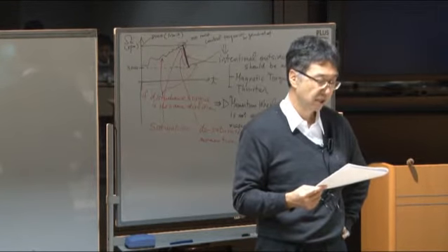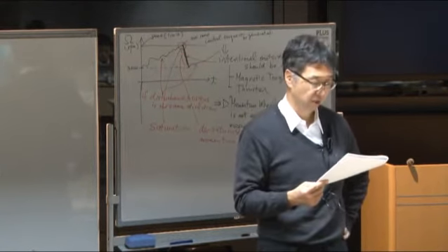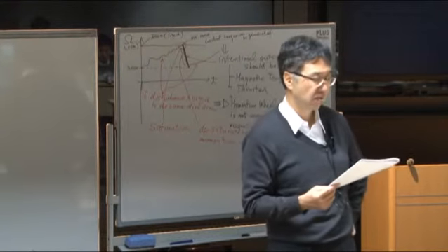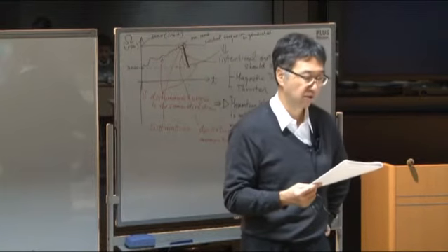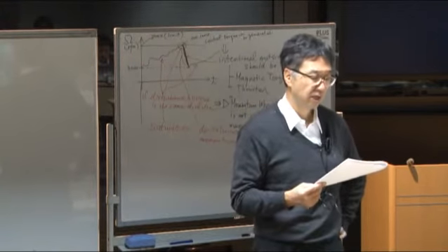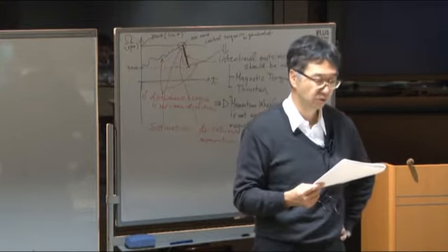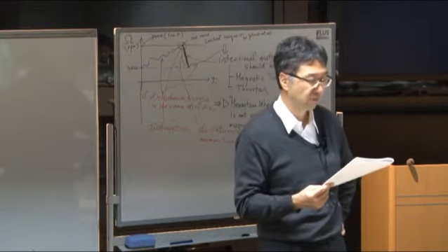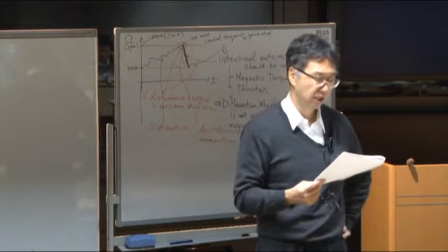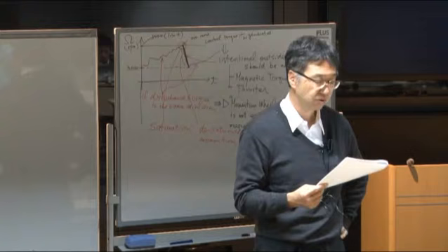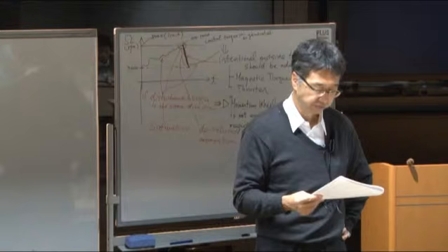Okay, so dual spin satellite has two meanings. One meaning is that this kind of long cylinder is possible without violating the stability requirement. So this is very good for installing in the rocket fairing. Another merit of this kind of dual spin is that you have the platform which does not rotate very fast, so you can implement an antenna or camera on the platform because it does not rotate very fast. Okay, so this is a dual spin satellite.